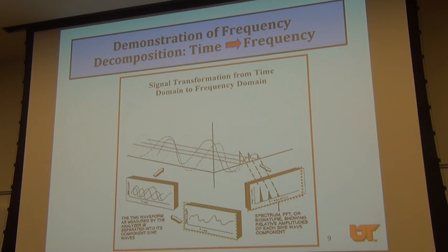So invariably you have to do this. If you have a general random signal coming from an accelerometer or any sensor, and you are interested in the frequency features, characteristics of this signal, then you have to transform from the time domain to the frequency domain, right? And this is not the best way to do it. You can do it, but it's not really practical. So you need to have more advanced techniques for converting or going from the time domain to the frequency domain.